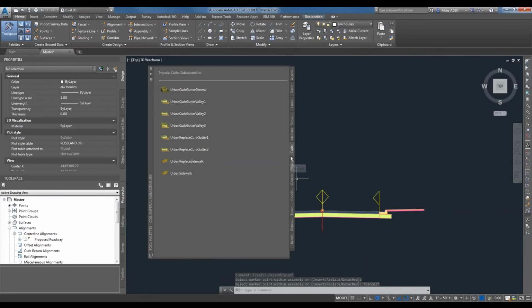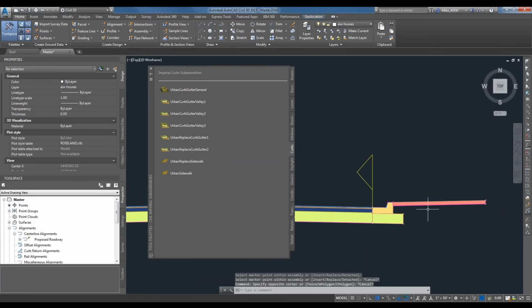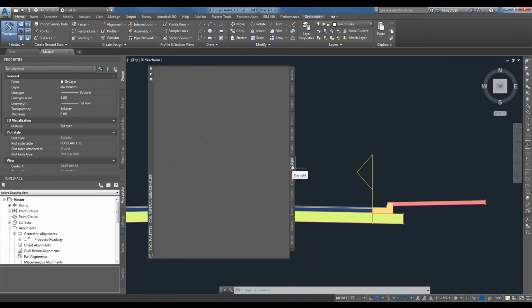So then next, we have our lane, we have our curbs, and we have our sidewalk. Next, you want to figure out how this is going to connect to our original surface. So at the end of the day, we're trying to make a design over here. We are going to be placing this somewhere in the world. So how do I tie this guy in to the rest of my existing topography? So that's where you go to daylight.